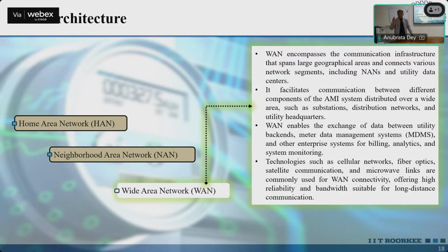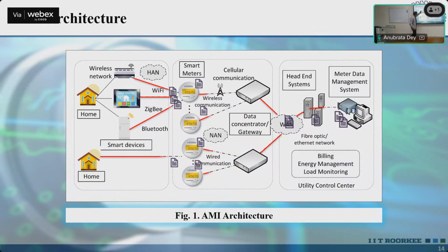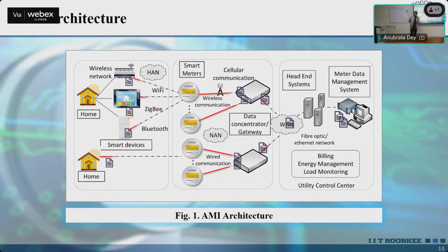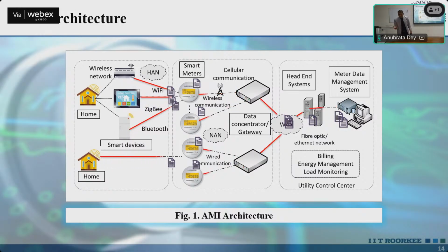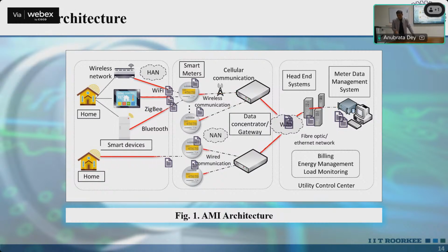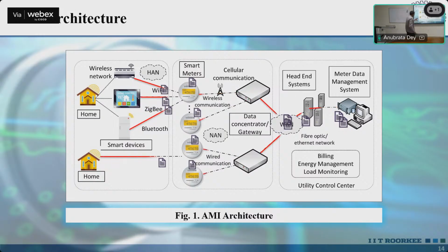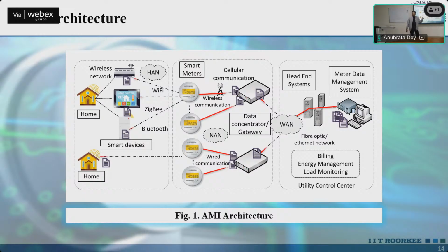No, it means only one. See, the communication network is single, and they are going to connect the data from your smart meter. This is the architecture which I have shown. That does not mean that we are collecting the data from all devices. It is already there in the smart meters. The smart meter is going to collect the data, whatever, let's say power. I think there are 23 parameters. But I have just shown that this may be possible.